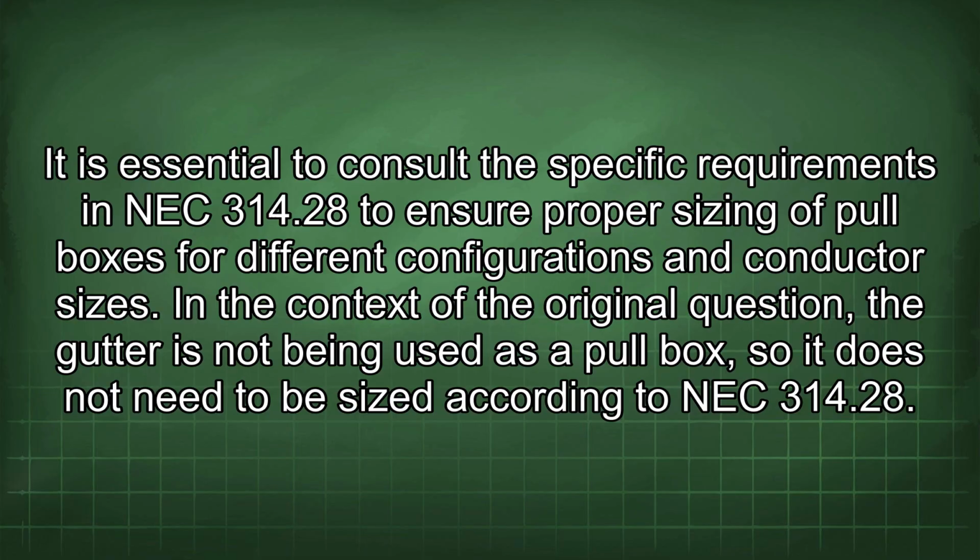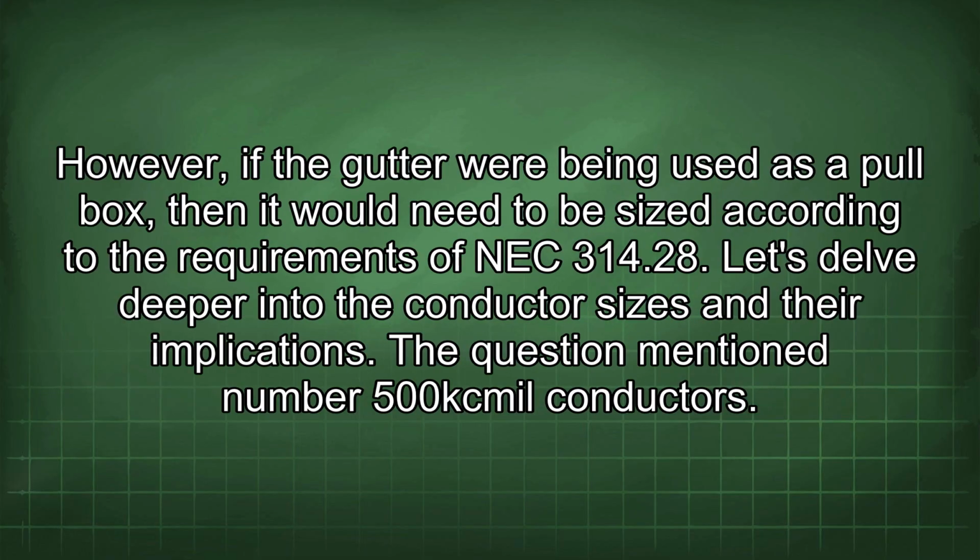In the context of the original question, the gutter is not being used as a pull box, so it does not need to be sized according to NEC 314.28. However, if the gutter were being used as a pull box, then it would need to be sized according to the requirements of NEC 314.28. Let's delve deeper into the conductor sizes and their implications.